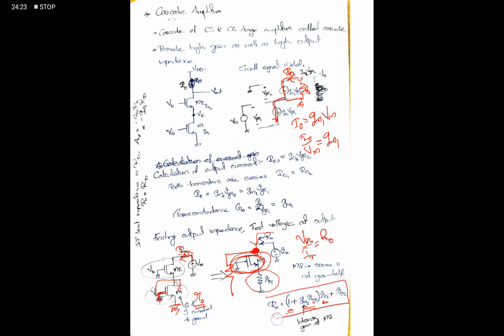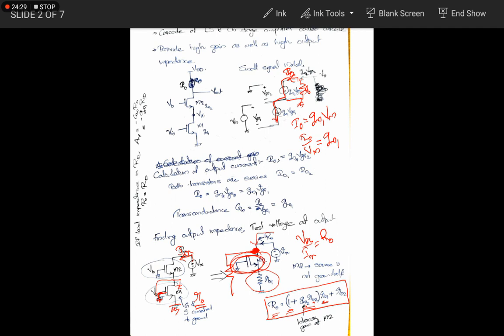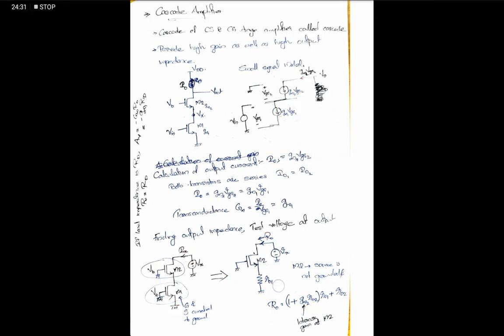This formula is very important because we will apply it in the next derivation. So I am repeating the same. In the output impedance calculation, in the source there is a resistance R01. If we reflect that resistance to its drain, the equivalent resistance value is nothing but R01 into 1 plus the gain of that given amplifier.